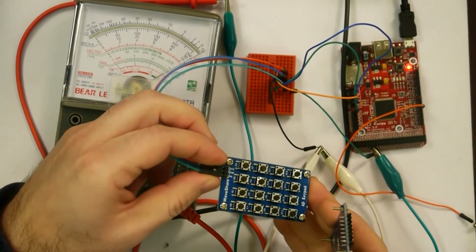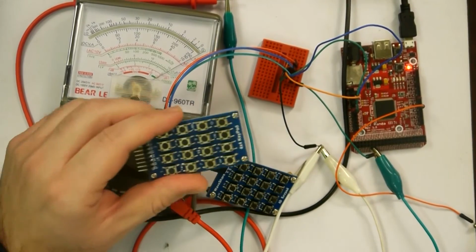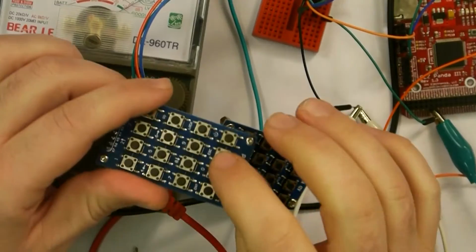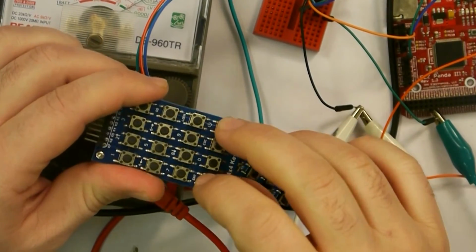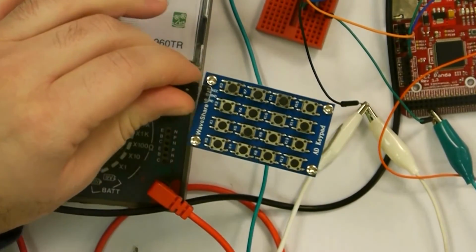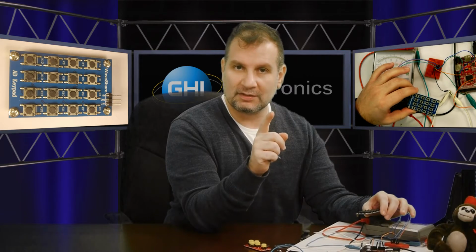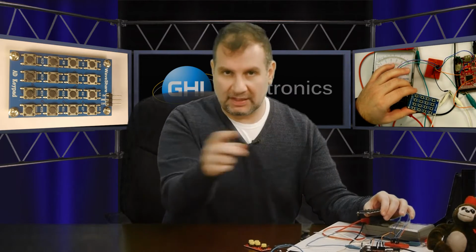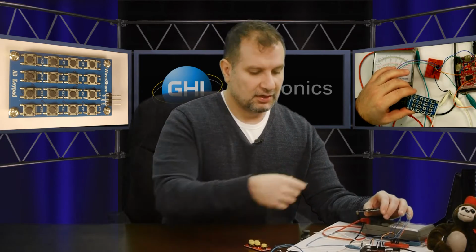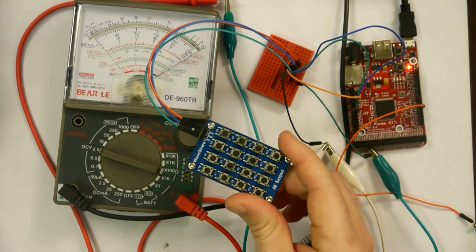Now, the disadvantage of this one is that you have to scan one row at once, meaning you cannot press 2 buttons at the same time in a row. You can do it in a column, where on this one, you cannot press 2 buttons at once. You can only press 1 button at once and detect that button. If you have them connected individually, then all buttons would work. So let's say in this application, it's okay to have one button at a time. Let's turn the audio on.